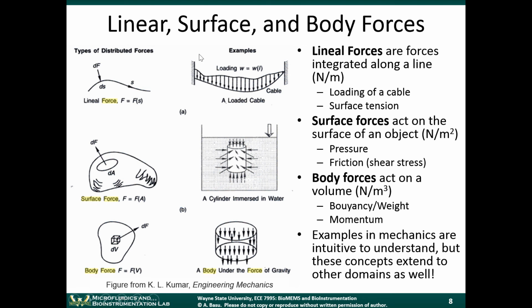So you can see these force vectors here. The force is distributed over the length of the cable. So lineal forces are forces that are integrated along a line. If you want to find the total force on this cable, you have to integrate the force contributions of all these vectors, and you're going to integrate it along one dimension, the length of the line.